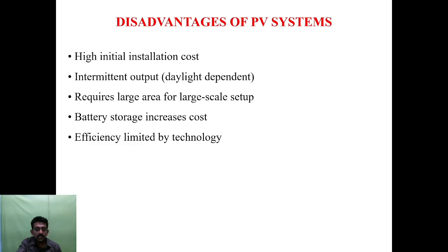Nowadays, as crystalline is being used, the efficiency is not doubled, it has just increased to 15 to 22%, which is seen as low efficiency for a generating unit producing power. A diesel engine power plant or any thermal power plant produces nearly 40% output efficiency. Compared to thermal and nuclear power plants, it is very low, and this becomes one of the disadvantages of the PV system.